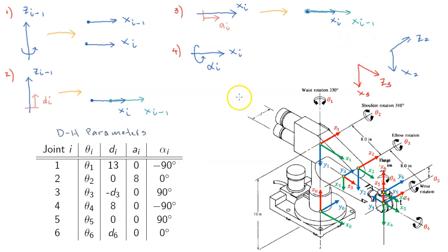All right, so now our coordinate frame would be here because we have just translated. So this is z2 and x2 will be here. So we want to find a3. a3 is how much we have to translate coordinate frame 2 in x3 to make the origins coincide. The origins are already the same, right? So we don't have to translate.